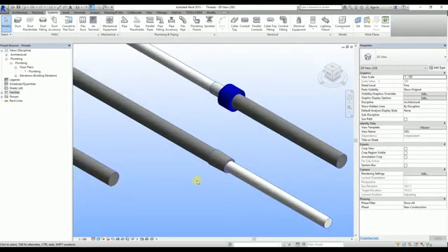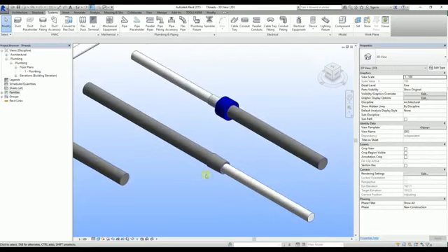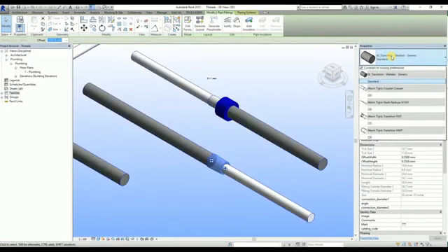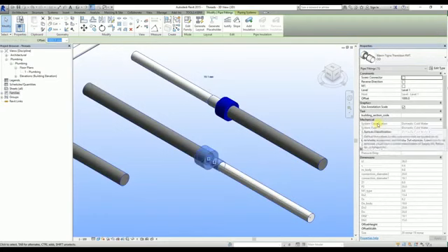In this case, the fitting inserted does not come from the Tigris package. In order to insert a Tigris transition fitting, we need to take the same action as in the previous steps. The fitting has to be selected and its type changed into the desired threaded fitting.